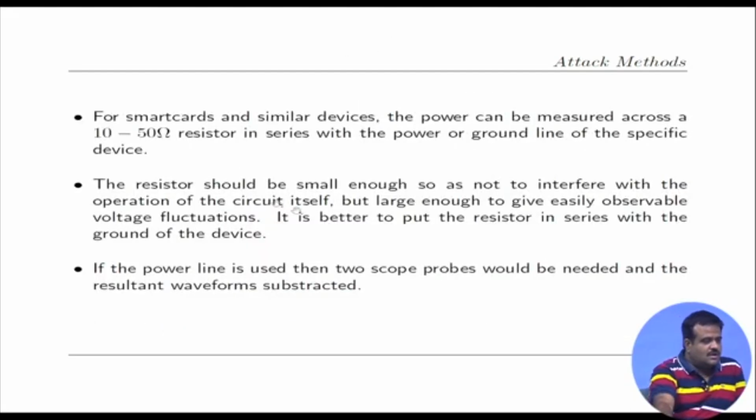For smart cards and similar devices, the power can be measured across a 10 to 50 ohm resistor in series with the power or ground line of the device.